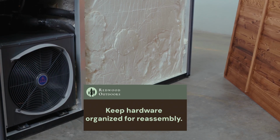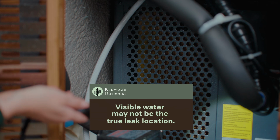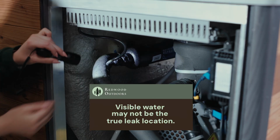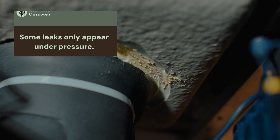The Denali uses spray foam insulation around the tub shell. Because of this, water can travel before becoming visible. A leak near a jet, light, or fitting may appear several inches away once the water moves through foam or framing. When diagnosing leaks, always trace moisture upward and inward toward the highest wet point possible.